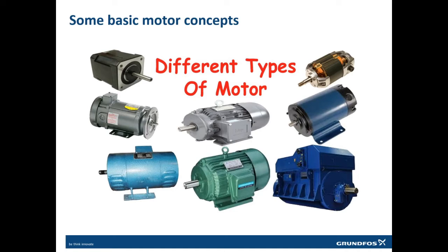But a pump is rotating at 3560 rpm, and usually the amount of water we use in our daily houses is 10 meter cube per hour or 20 meter cube per hour. This is the standard range of pumps in our house. So different demands ask for different motors, and that's why we have many kinds of motors.